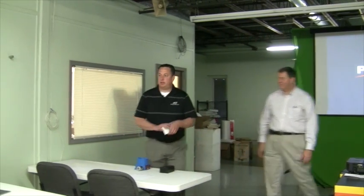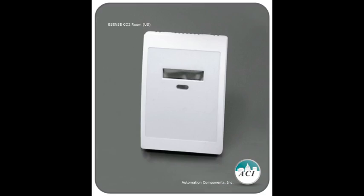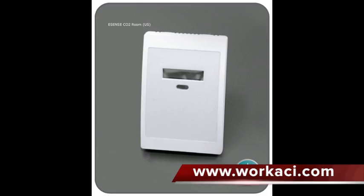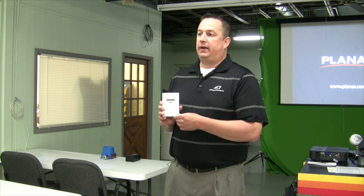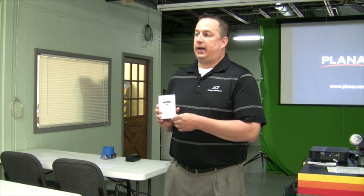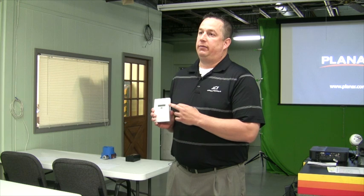I actually will go over the CO2 sensor again. I know we covered this in the PowerPoint, but we have these for wall mount CO2 sensors. It's going to be our A-Sense and E-Sense line. So if you go to workaci.com and look for carbon dioxide CO2, it's going to be the A-Sense and E-Sense. The E-Sense is going to be just the plain CO2 wall mount sensor with 4 to 20, 0 to 5, 0 to 10. The A-Sense is going to have the relay versions and also the display versions.